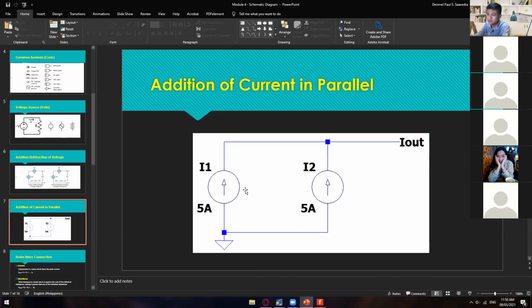And in here, we could also have a current source, just to improve the flow of current. So it's not always the voltage source. Sometimes you could also have a current source wherein you can improve the current to this output. To do that, you have to connect them in parallel connection. In that case, 5 amps here and another 5 amps here, so they will be added at this point, and you will get 10 amperes. So that's how you increase the current on a certain circuit.